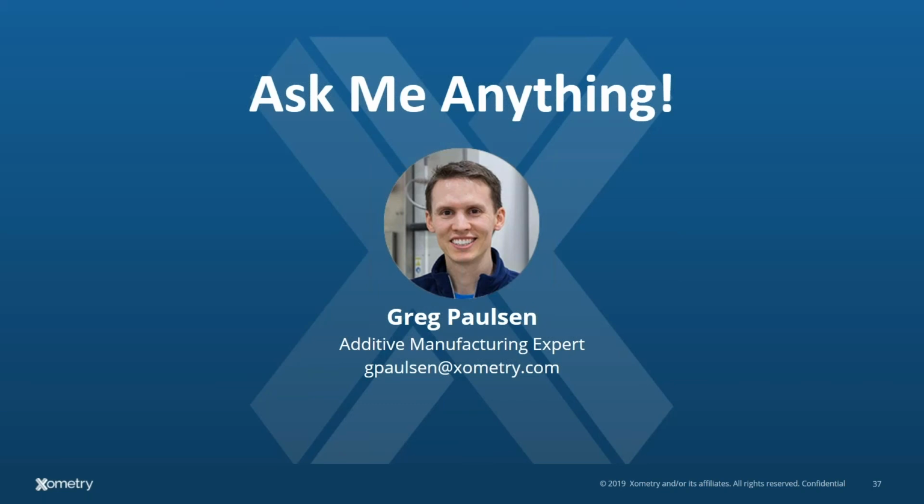about your exact needs. But I can tell you that I've done testing with SLS nylon, and multi-jet fusion will act the same way, where it's able to get that low. And if I drop it, it's going to be stiffer. It's going to be below freezing, so it'll be more prone to snapping. But it still will thaw out and not have any overall problems.